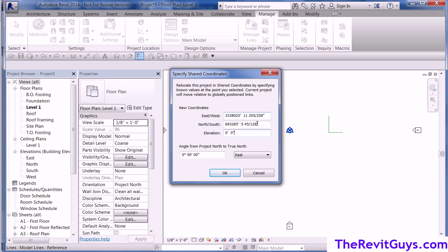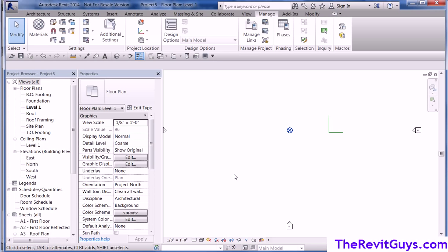Now I told Revit that point is the one in our project, and we hit enter. Now what happened is you'll notice that there's a circular point here, but the triangular one left. If I zoom out way, which I probably couldn't even zoom that far, it would show that little triangle, which is my survey point. Now here's where it gets kind of cool. I told Revit, in essence, where 0 was, way that way.